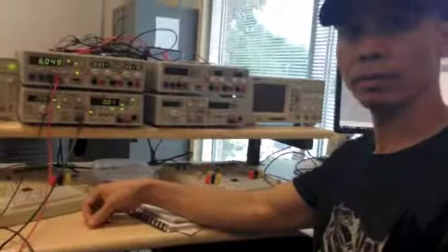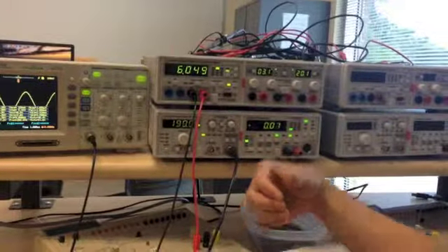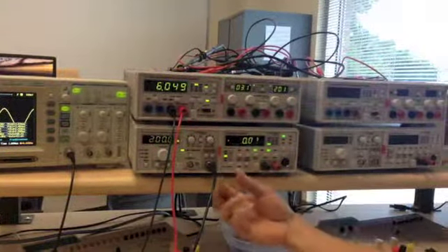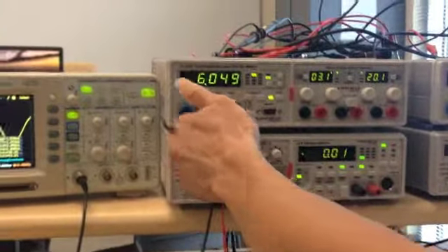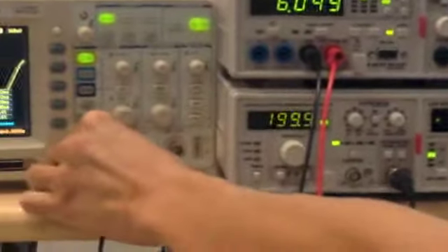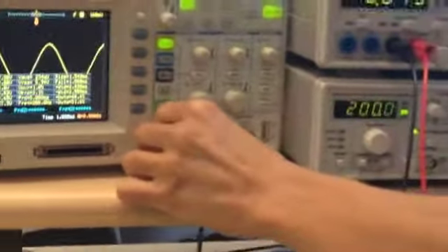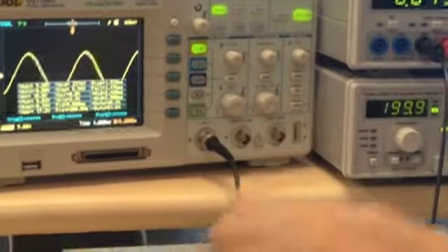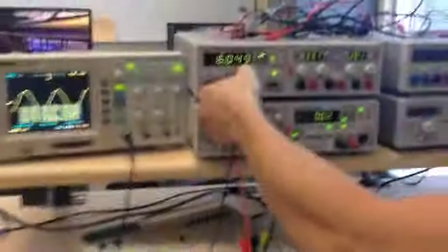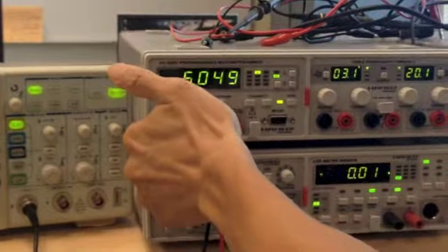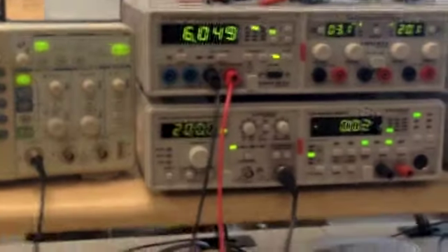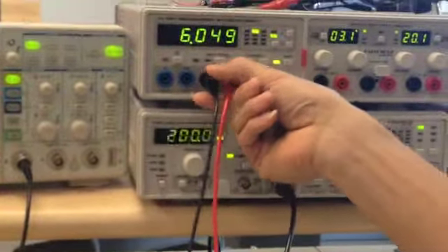My name is Phommachak. I'm doing the bench portion of the demo. First, what I do is connect all these cables. Function generator cables connected to the function generator, and the oscilloscope cable connected to channel 1 for the V in, and then positive and negative leads connected from the digital multimeter to the positive and negative ports.